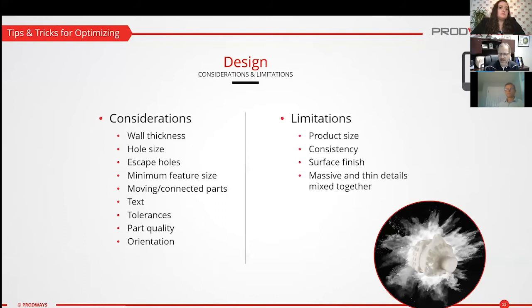For instance, nesting, you can run an 8 to 10% density in your nest, and that is very feasible with the SLS technology. How you nest, there's software out there. I happen to do it old school. I nest it myself on the screen for every build, but that's a major advantage, and the software can help with that. So those are some basic design considerations. Again, some of those can be varied by materials as we move on to look at the basic material options that we have.